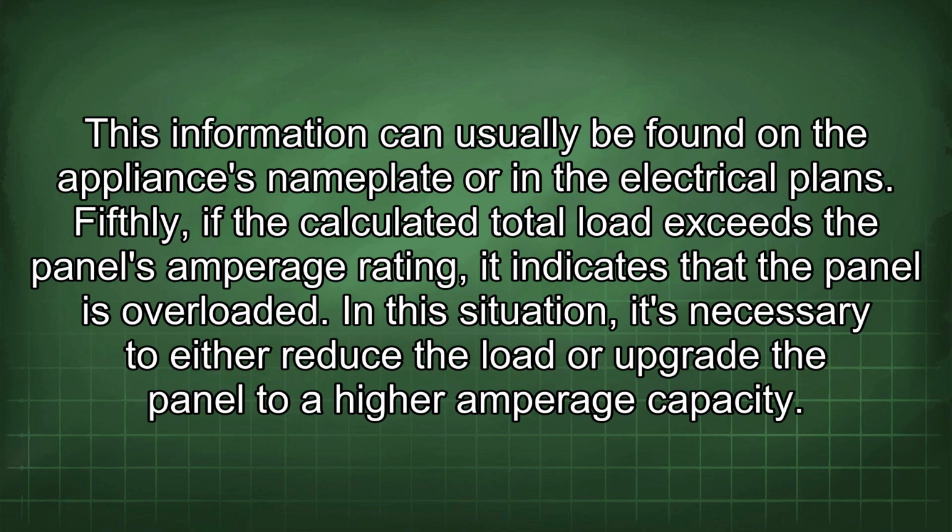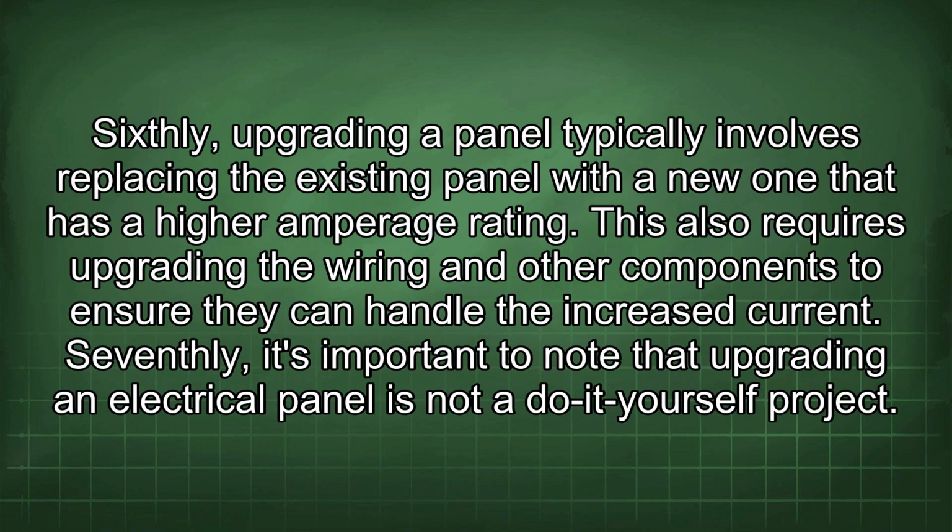Fifthly, if the calculated total load exceeds the panel's amperage rating, it indicates that the panel is overloaded. In this situation, it's necessary to either reduce the load or upgrade the panel to a higher amperage capacity. Sixthly, upgrading a panel typically involves replacing the existing panel with a new one that has a higher amperage rating. This also requires upgrading the wiring and other components to ensure they can handle the increased current.